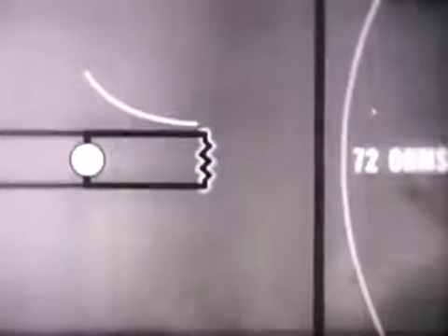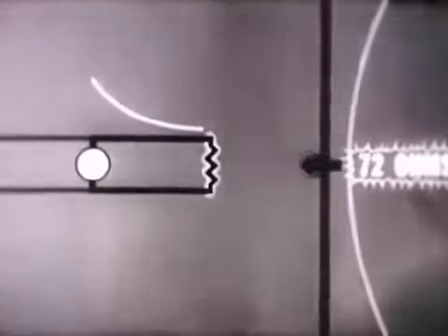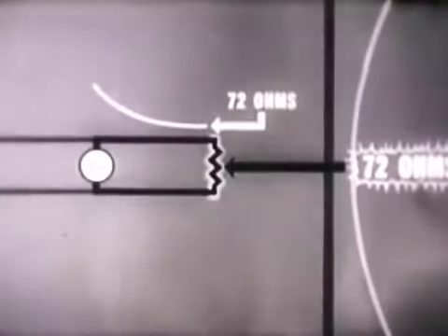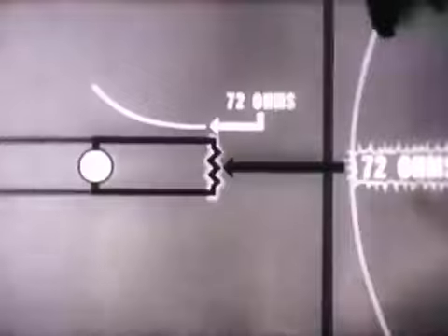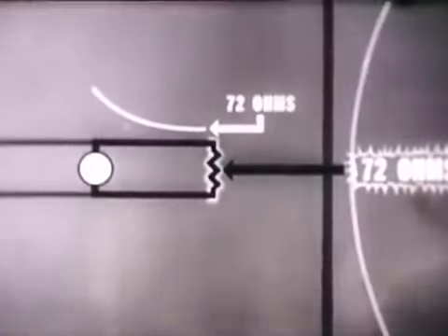Another method of impedance matching employs two lengths of metal tubing called a quarter wave matching transformer, or Q-bars. These tubes are merely the twin wires of our old friend, the quarter wavelength resonant line. In this simple closed line, the impedance curve is minimum at the closed end and maximum at the other. Now, supposing we put a resistor in the closed end of the line, say 72 ohms. Now we know that our impedance value at this point is 72 ohms. This changes our curve a bit, decreasing the impedance value at the generator end of the line because the standing wave is no longer at maximum amplitude.